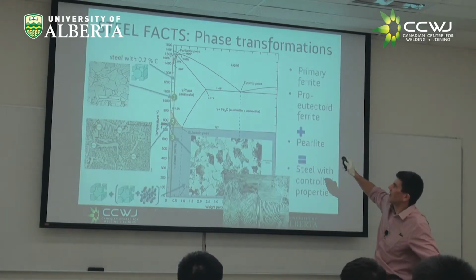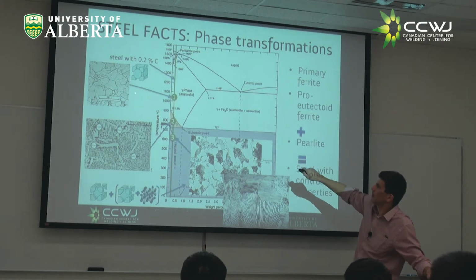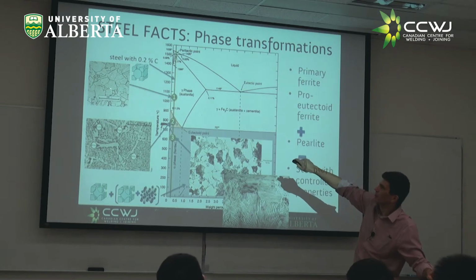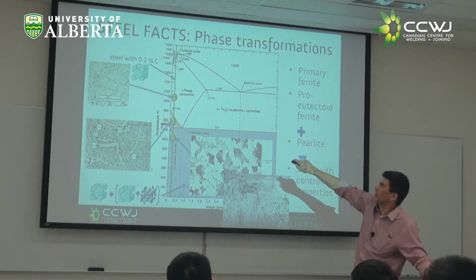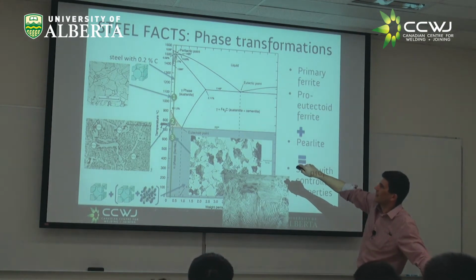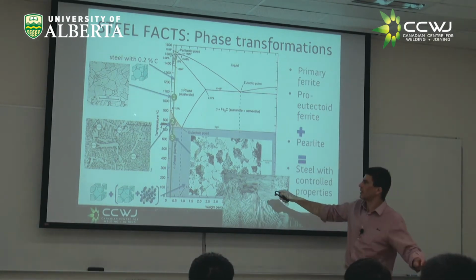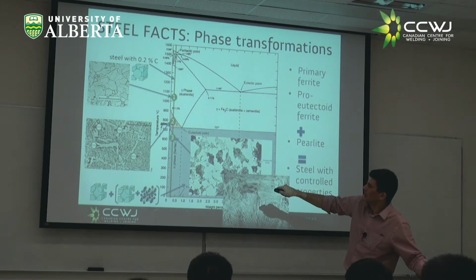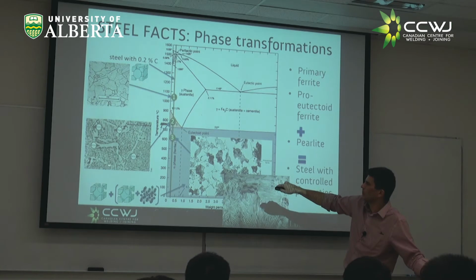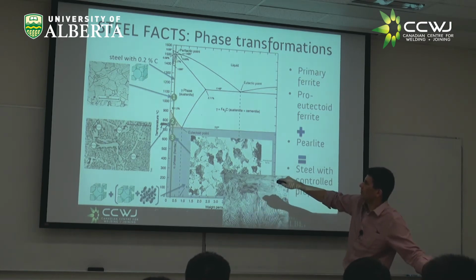I think here I have some microstructures of what would look like the microstructure of a steel at different temperatures. Here we're in pure austenite, so the steel would look something like this. These are the grains of austenite at high temperatures, the FCC. If we're here, and the name for here is the intercritical region, at least in welding, that's what we call it, you would see some amounts of ferrite and some amounts of austenite. In this case, it looks all kind of weird here. That used to be austenite, and now it became something else, which we are going to discuss. A mixture of the two.